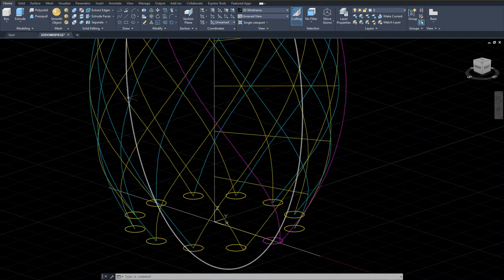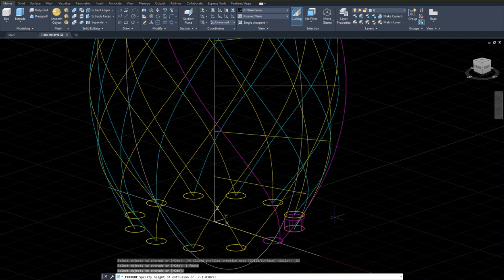And save, of course. Control S for save. If you have a power breakdown or anything, okay, having saved your work definitely pays off. Okay. So let's go to extrude option again, or you can hit enter for extrude option. Okay. And extrude. Okay, select the circle. Okay, enter. Select the path option.